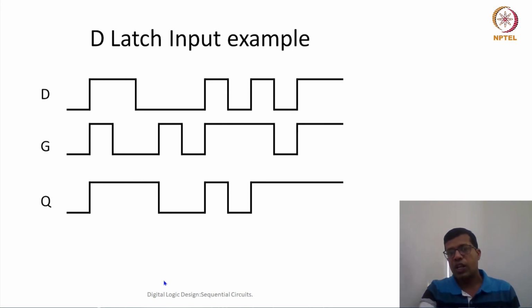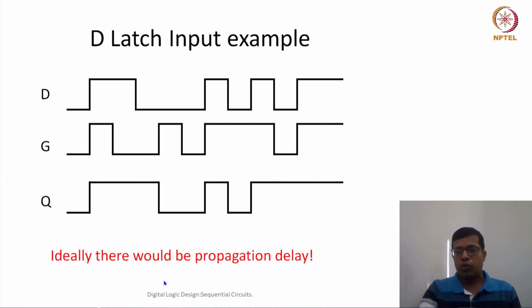So with this, I would like to close my lecture, with one more comment. The waveforms we have created consider that the delay of this D latch is almost 0. But in critical scenarios, the propagation delay is important, as it would decide what the final output would be.